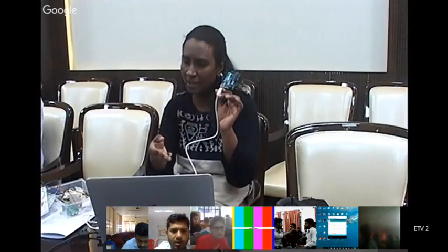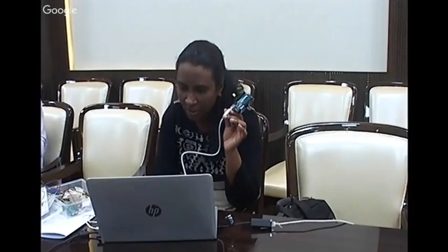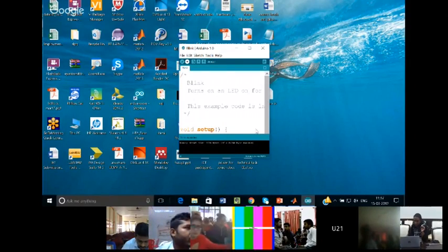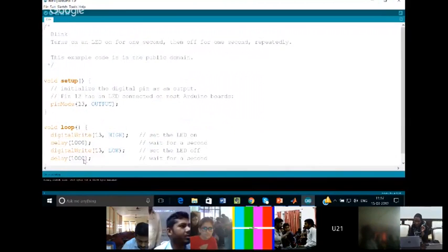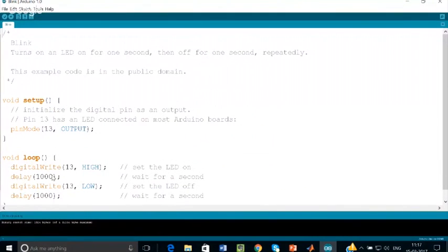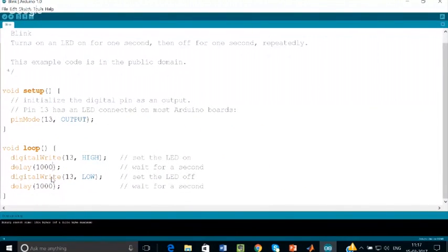If I want to change the timing, I just change the 1000. If I change it, automatically the blinking speed will change. So once again, if you want to see that, let me upload again and show you. Here, let me say high will be for a small time, let me keep it as 500, and low for a long time. Let it be like this. So I'm doing the uploading. Now it is uploaded.